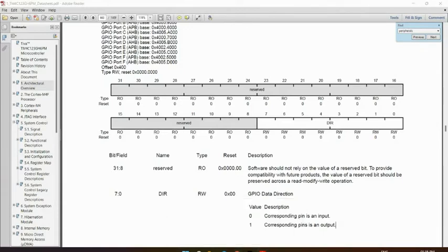Now we have to tell this particular microcontroller that we are going to use this pin, the LED pin, for digital read and digital write. Why? Because like I told you before, one pin can work in different modes. It can be analog, it can be timer, it can be a UART pin, it can be SSI, and so on. So whether you are going to use it for ADC or some other purposes, you have to specify it. So now here we have to specify that this pin will be a digital pin. Which pin? The LED pin.